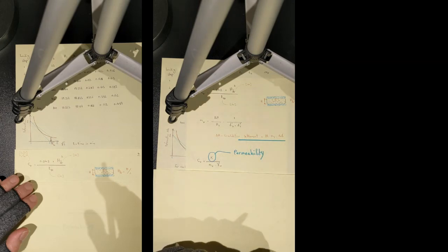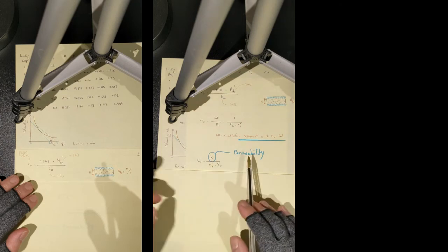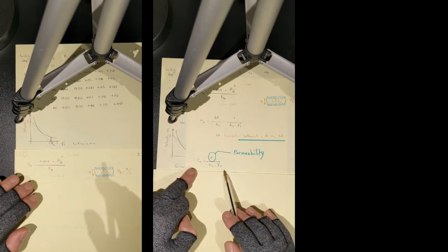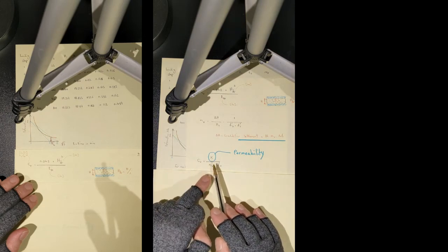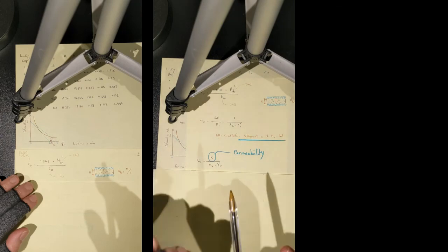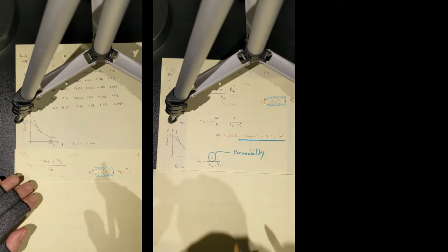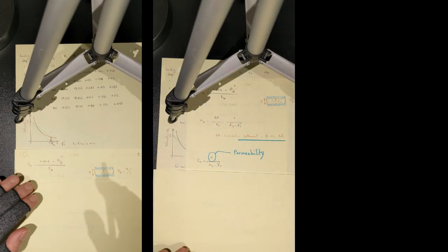And K on top is your permeability. Depending on the units that you're using here, you can control the dimensions or units of permeability. So you can see that you can measure the permeability of your clay soil at the same time as you are measuring the consolidation parameters for your soil specimen. So pretty much useful.